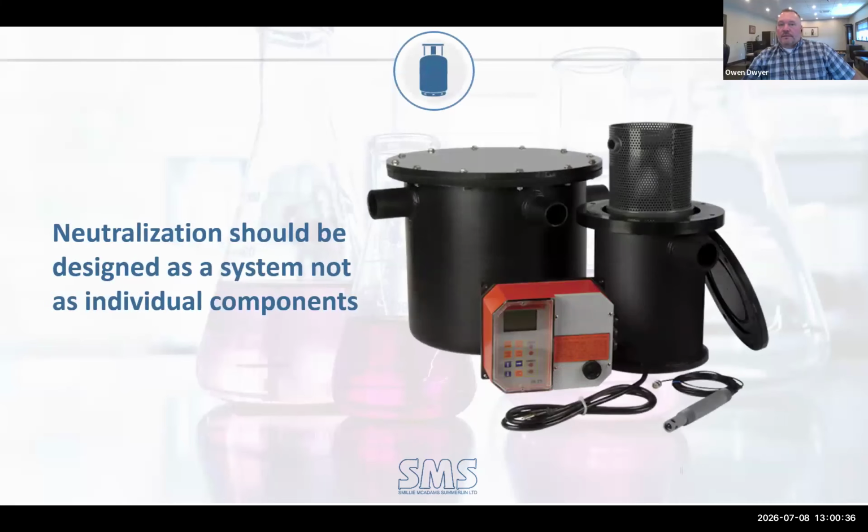So it should be thought of as a system. Not only is it your pipe and fittings and all of that we talked about, but the neutralization system is pH monitors, injection of calcium carbonate, as well as the interceptors. So think of it kind of like as a one package.